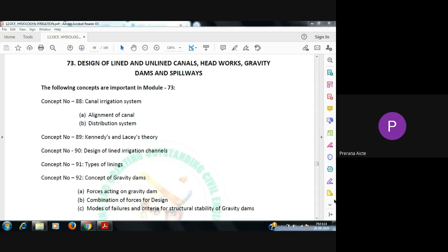Then the important topic of groundwater hydrology. In groundwater hydrology, the main thing is discharge through aquifers. So there are 4 definitions: aquifer, aquifuge, aquitard, aquiclude. These are all important. One may contain water and transmit water, one may contain water but not transmit water, and one neither contains water nor transmits water. That's all. If you classify these things, you can remember the definitions very easily.